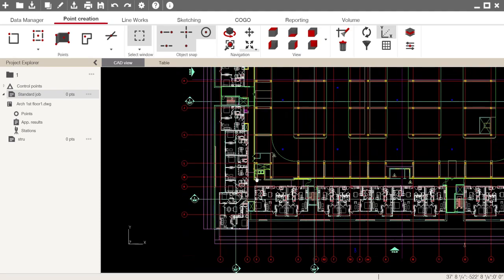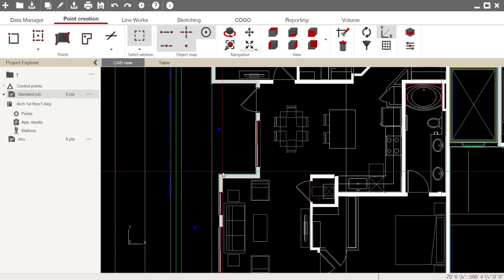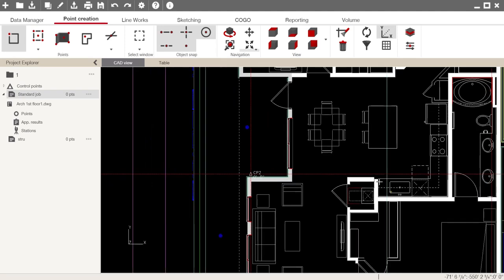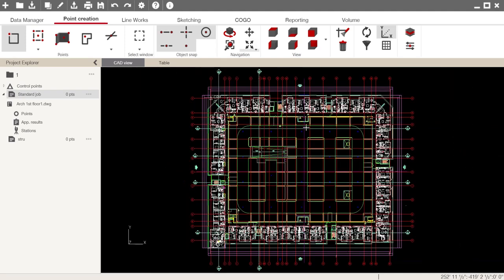And then let's just go down here because I believe 1P is also on my structural drawing. So I'm going to zoom in there. I'm going to create a point, and I'm going to put it right here on that intersection. Make sure you zoom in all the way so it's directly on the intersection. We don't make a mistake. I'm just doing this really fast for an example. I'm going to zoom back out now. I've got a control point on grid intersection 1A and 1P.